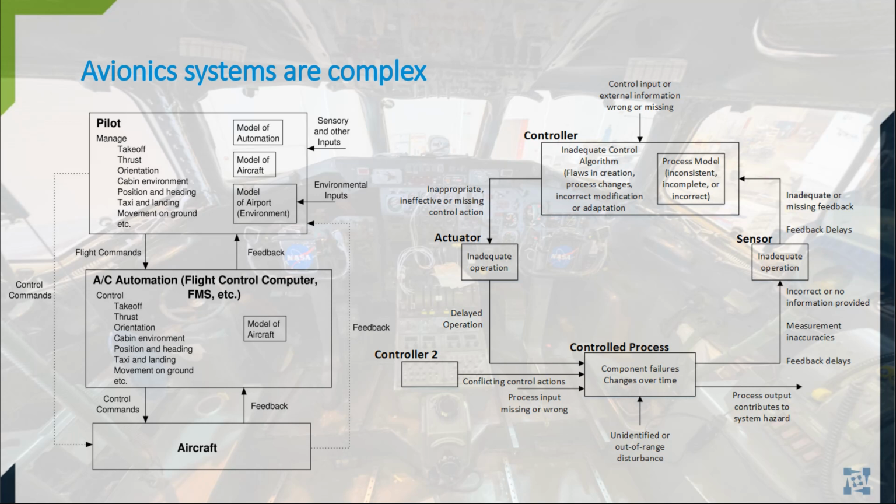And it's funny because developers who are new to avionics systems might be used to what we like to call the happy path software, right? We look and say, okay, well, the sensor says this, and everything is good, and we'll do a high number, we'll do a low number, and we're good. We do a happy path and a couple of less than happy paths. But when we're doing avionics systems, we have to really think hard about what are all the possible use cases and what do we do when these things happen to make sure to maintain the safety of the aircraft and